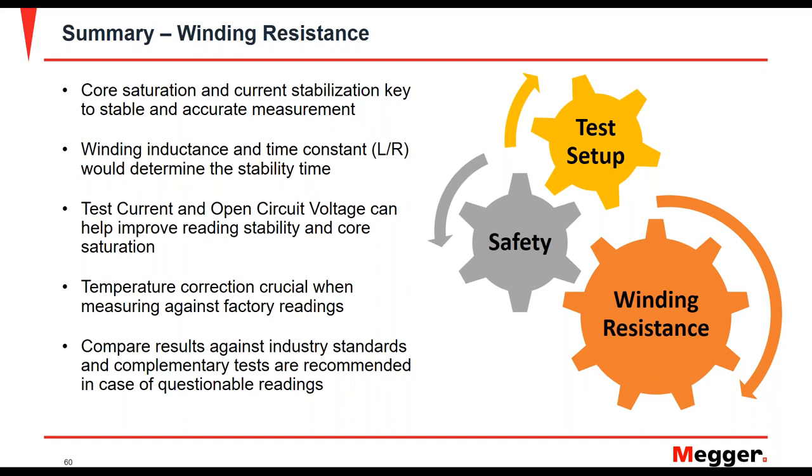Of course, considering the fact that temperature is a key factor in resistance measurement, temperature correction should be made when we are comparing, especially with factory results. And comparing with other industry standards and with other complementary tests becomes very important when questionable results occur.